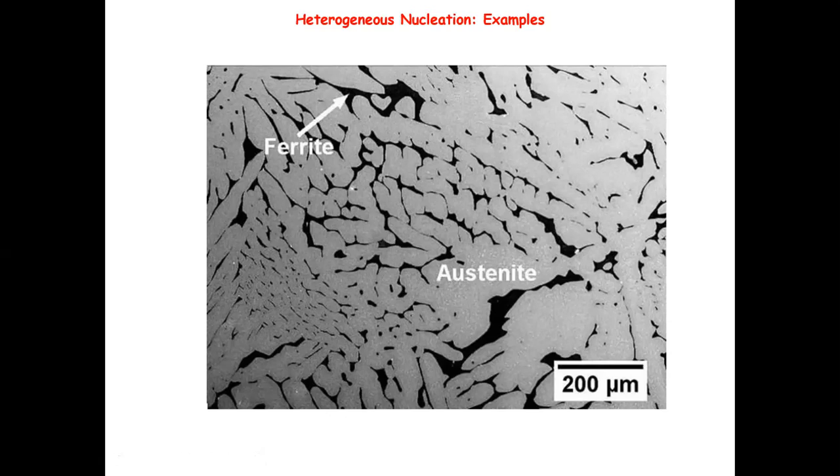Without even looking at the EBSD data, you can already see the shape of the grains. So this is very intuitive evidence indicating that heterogeneous nucleation is much more frequent and much easier to occur in most solid-solid transformations. After the transformation at room temperature, most of the secondary phase precipitates are on the grain boundaries, they grow along the grain boundary, and they trace the grains. This indicates that they form on the grain boundary, and you won't see a lot of homogeneous nuclei.